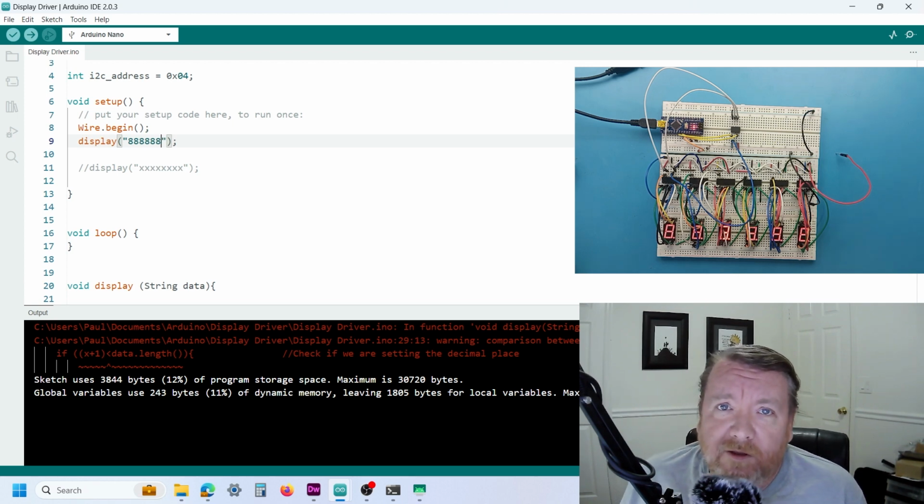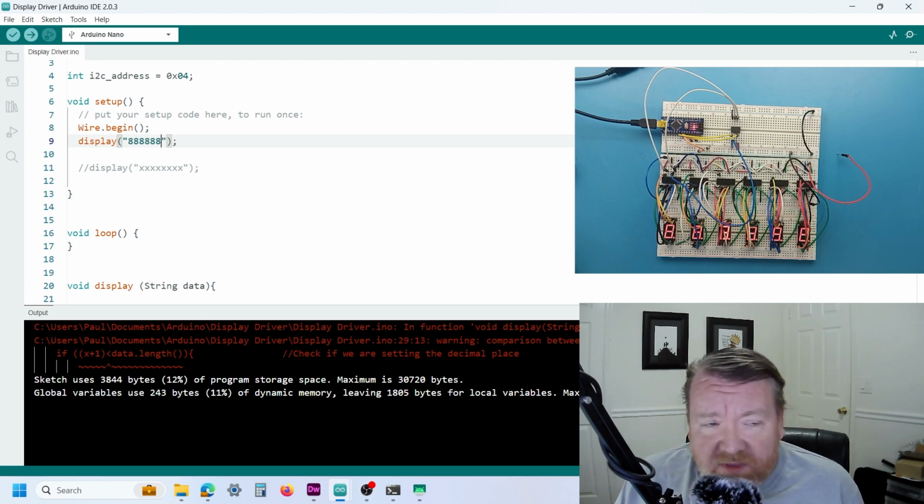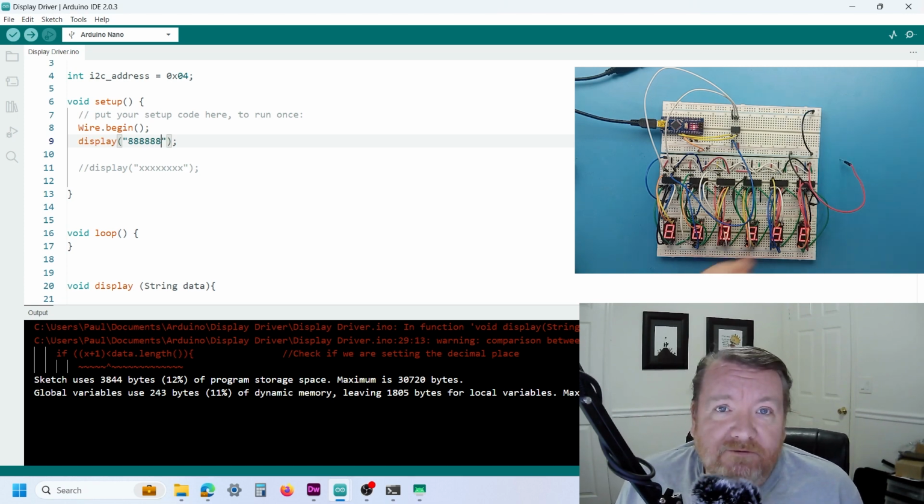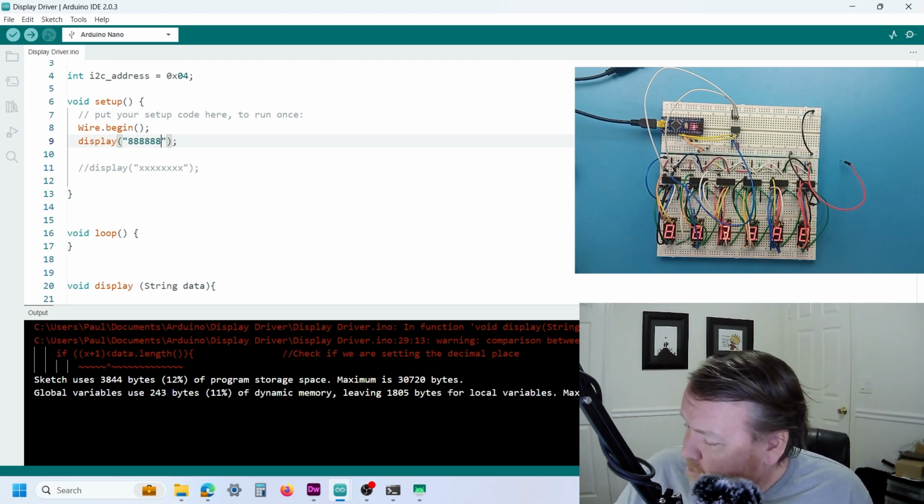This is a perfect example that if you have unused pins on any of the logic devices, you don't want to leave them floating high or floating low. You really should tie them high or tie them low with a resistor to prevent them going through random events. In this situation, it just turned out that even without the VCC lines coming through, we can still get power coming through to the output, which is completely undesirable.